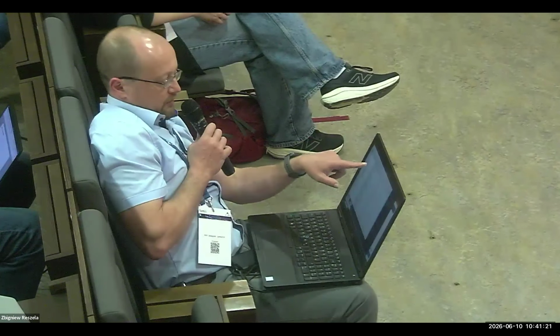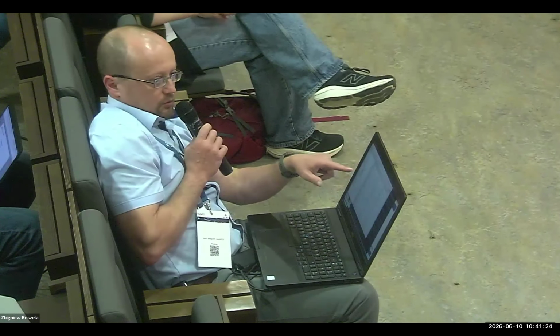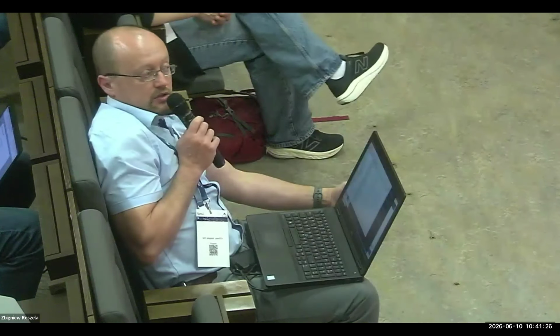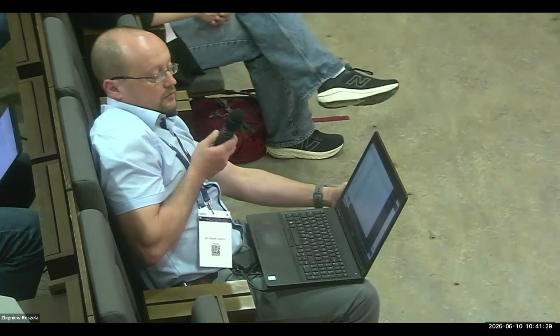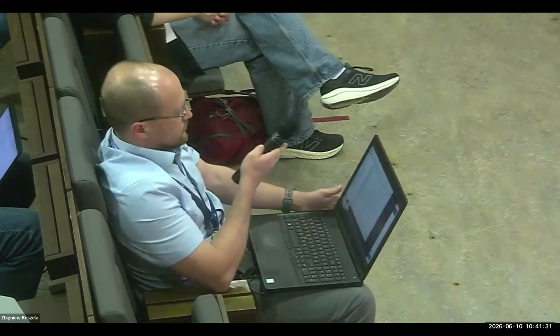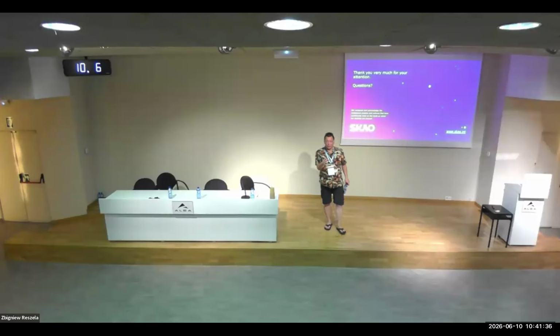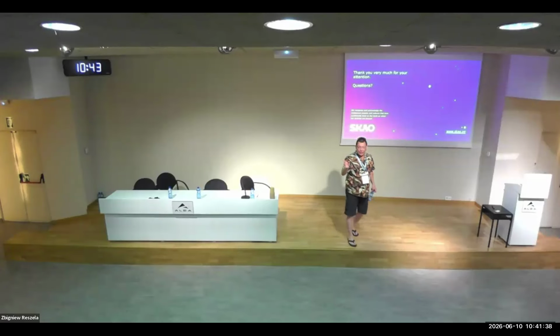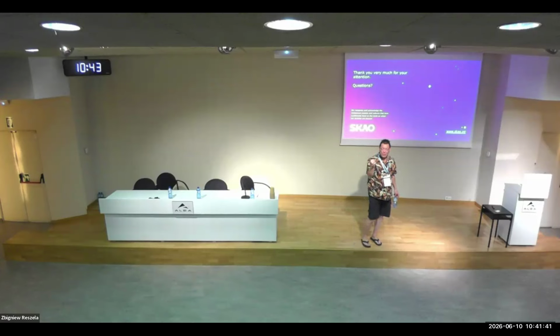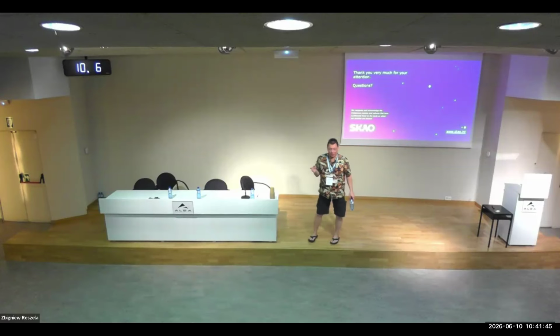Here in Jive, we have the change event, the archive event, and we'd also like to add a slide for alarms. The alarm event is for free, as a matter of fact. We implemented it in such a way that you just subscribe to it. There's no configuration necessary. It's built in. If you have min warning, max warning, min alarm, max alarm set, you can subscribe to the alarm event automatically. It's done for you. That was a very good decision made by Thomas Ives for us.